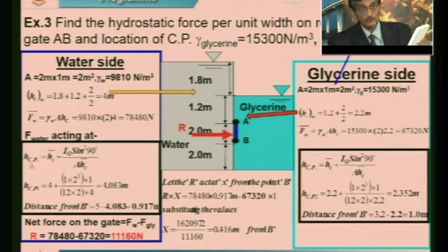We go back to our formula, my dear friends. You can see on the left side, the water side, where is the location? It means this side I want to locate. Formula is Hc, which is 4, plus Ig, Bd cube by 12, 1 into 2 cube by 12, sin square 90, 1, divided by area, same value, into 4, you can calculate.